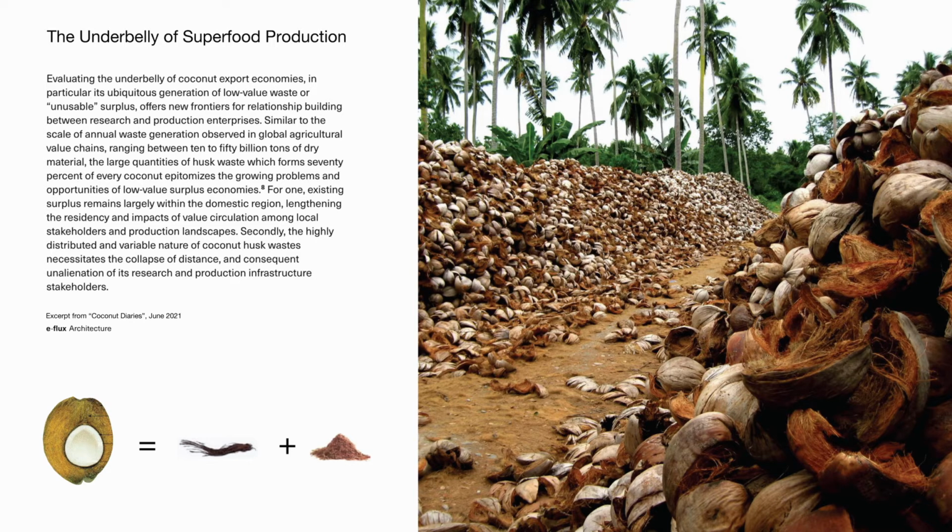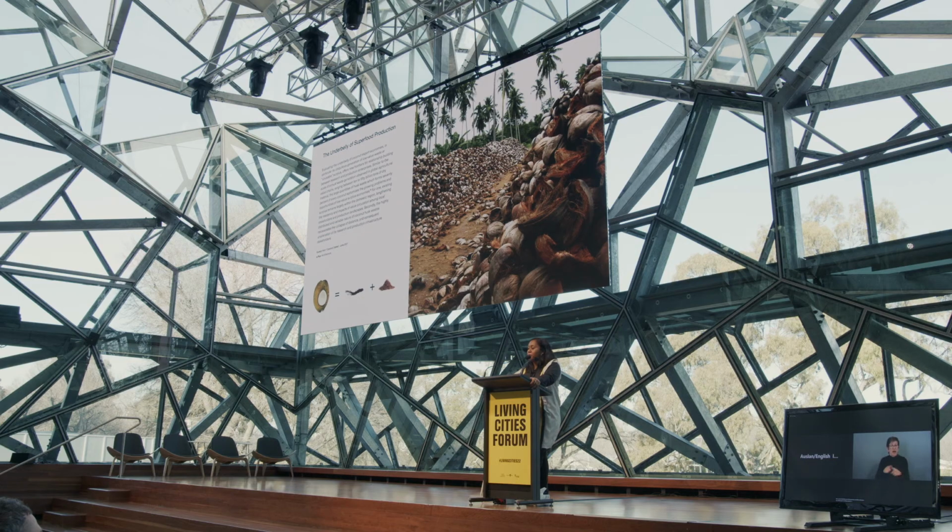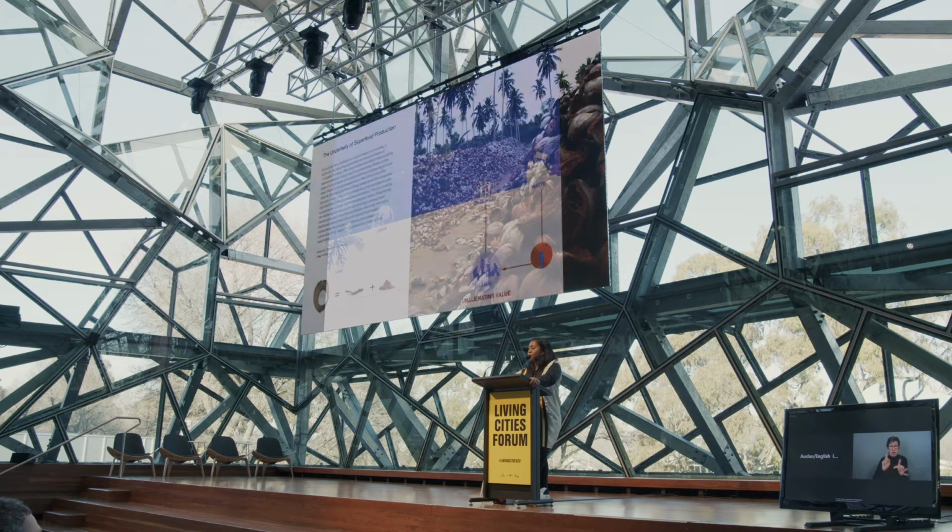And when you decompose the husk itself, you get this wonderful tensile fiber, coconut fiber. And what we discovered, a majority of the husk was made out of this dust-like substance called the pith, which is typically used in hydroponic soil substitute applications. But when heat and pressure is applied to it, and this is half the processing conditions that you see when you're making plywood, it actually melts into a really uniform and robust glue. So essentially you eliminate the need for synthetic glue.